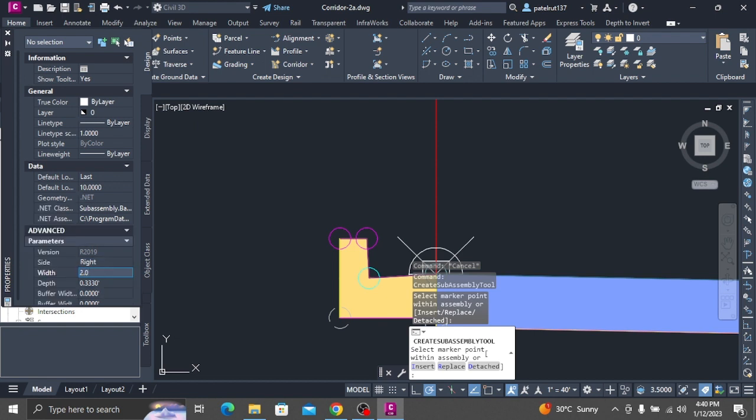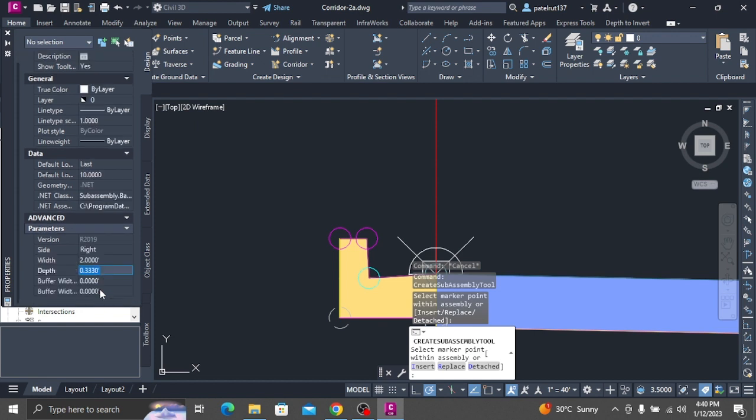In the Transition Alignment row for Basic Lane Transition, left-click the Object Name field. In the Set Width or Offset Target dialog box, in the Select Object Type to Target list, select Feature Lines, Survey Figures and Polylines. Click Select from Drawing. In the drawing, on the left side of the alignment, select the blue polyline and magenta feature line. Press Enter. Click OK. Specify the fixed lane elevation targets.